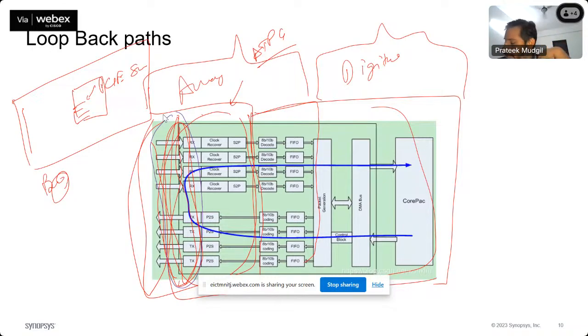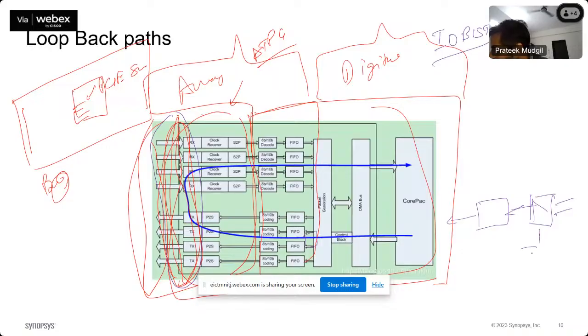So what we do is we have a kind of logic called IO-based loopbacks. Built-in self test, everyone knows it. When we go deep towards the ports, we are going towards the problems, because we are going to handle the physical world. So as soon as silicon fails, we have overrides here. We can say that this is a path. Let us say this is a FIFO, and data flows to this FIFO and then goes to the 8B/10B encoding and decoding logic. So we put a mux here, like this, and we have a controller here.